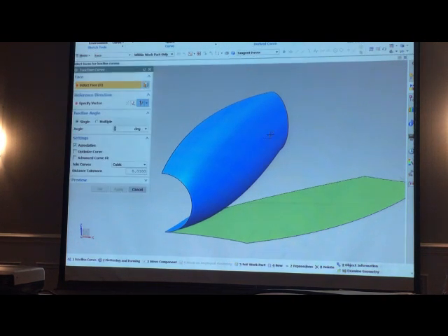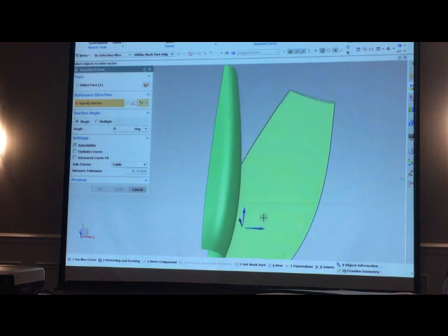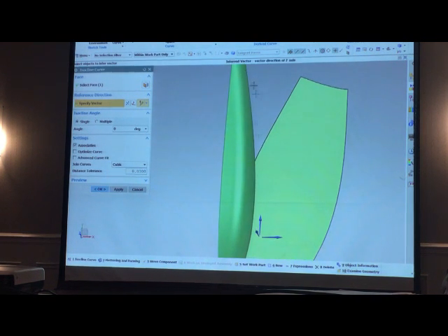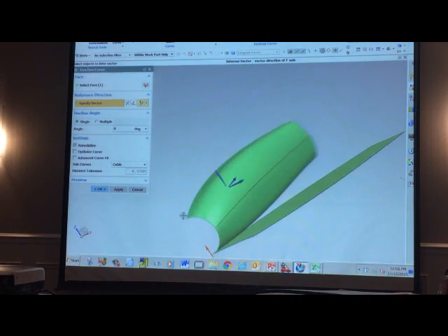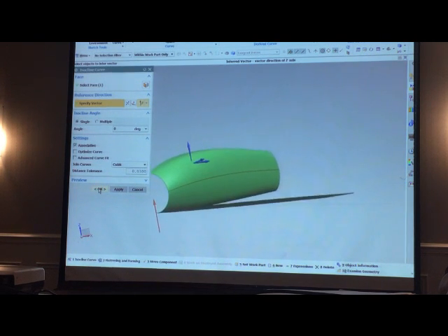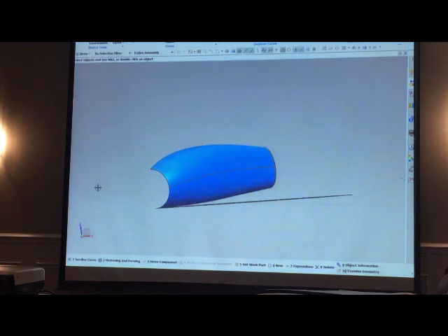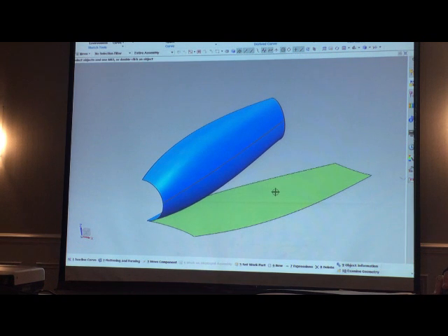So I'm going to do an isocline curve. I'm going to pick this surface, 0-degree isocline, looking straight down. That would be this angle here. It was basically the silhouette curve. So there's the silhouette curve, or the 0 isocline, if you want to call it that. Shadow curve, some people call it shadow curve. Now, let's go back to here.